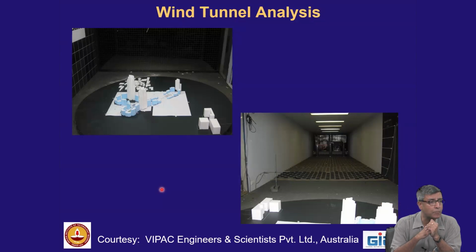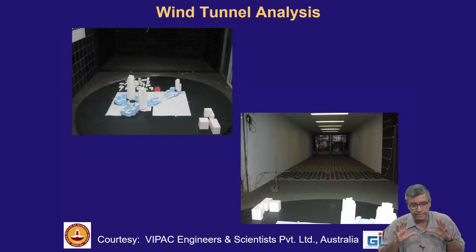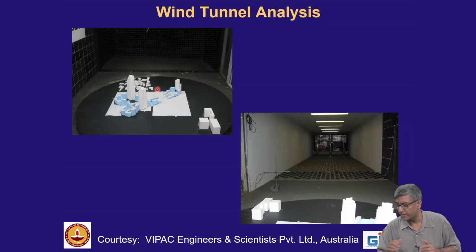That means if you get an opportunity to see a wind tunnel, you can see how they are doing it. In our campus, we of course have a wind tunnel for the aerospace department, but not for civil engineering. In a wind tunnel, you try to generate the landscape, and it is called boundary layer type of studies, so that you try to mimic what can happen due to the interference effects.